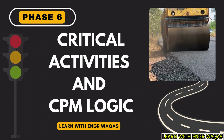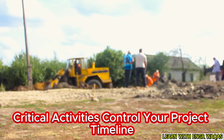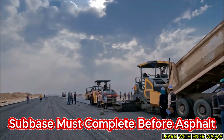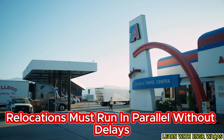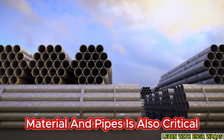Critical activities and CPM logic. While doing these road construction projects, civil engineers, attention over here. Critical activities control your project timeline. Earthwork must finish before sub-base. Sub-base must complete before asphalt. Drainage and utility relocations must run in parallel without delays. Procurement of asphalt material and pipes is also critical.